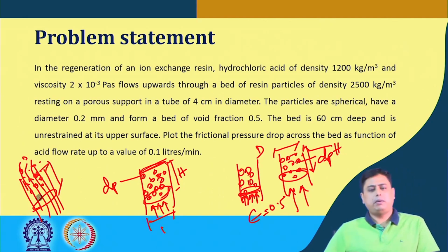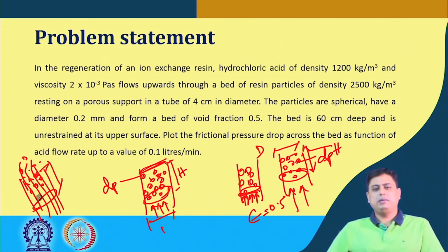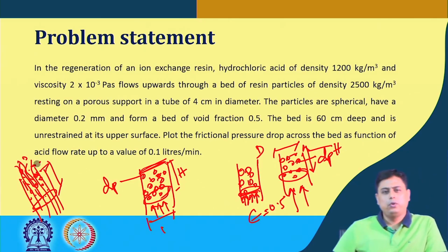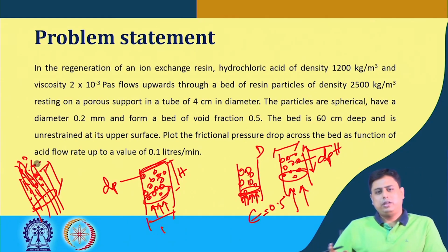The pressure drop after a certain point will not increase or decrease; it will be a constant value, because due to this disengagement of the particles there is now sufficient voidage that the fluid can flow without much resistance.